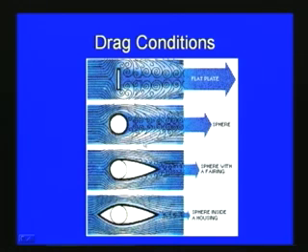So, if the same sphere is put in with a fairing like this, you can see that the boundary layer separation changes, and then instead of the pressure effect, the shear effect will be much higher, and then we have to consider this in the equation correspondingly.